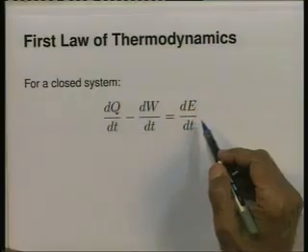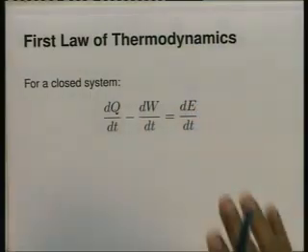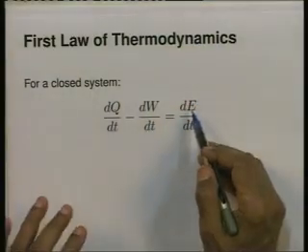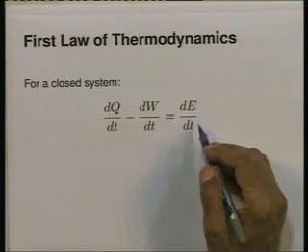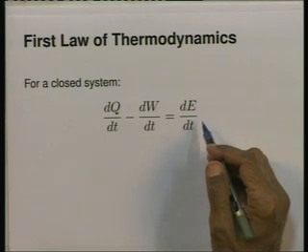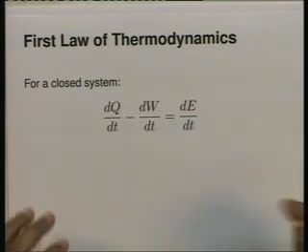Of course, for our problems it is the internal energy which is going to be the dominant one most of the times, but in general E refers to the sum of internal energy, kinetic energy and potential energy. So, this is a statement for the first law for a closed system.